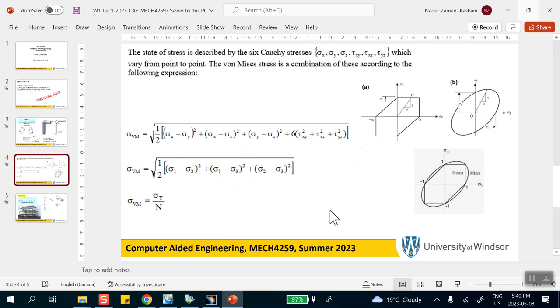The material has stayed elastic, so you remove the load, and the part is going to go back to its original configuration. But if it exceeds it, then those numbers that you get are totally nonsense, because you have pushed it into the plastic zone, and you're still pretending that it's a linear elastic problem.